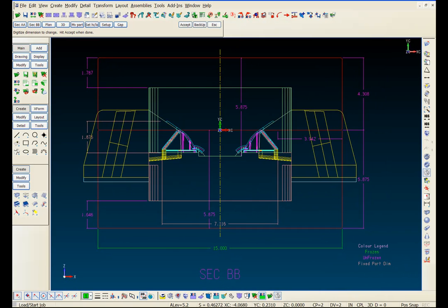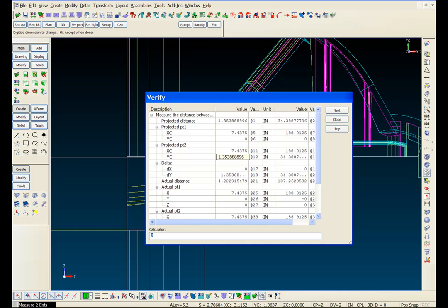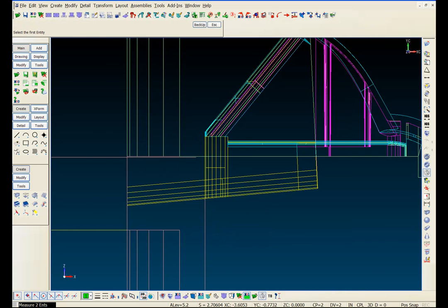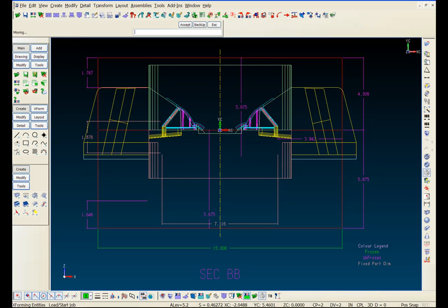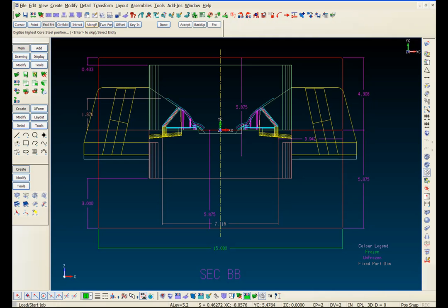So I have some modeled inserts and a modeled slide with my part here, and now I'm running it through the XMD standard mold base parameters dialog. The first thing I'm doing here is just getting a height where I want to establish my 0, and I'm going to tweak my part, just using the move part command. And now I'm going to go ahead and adjust my block sizes.